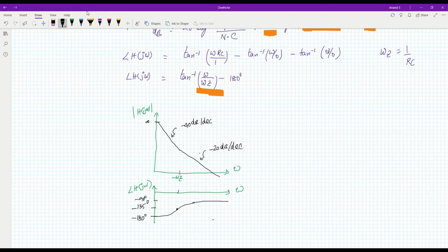So this is the Bode plot for the system after introducing a zero. Here we can see the frequency called the crossover frequency, where the gain is 1. At this frequency, the phase is minus 90 degrees. So this system will be stable.